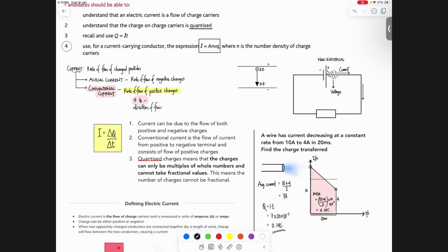So for example, a thermistor, you have heard of the thermistor, right? What does the thermistor do? As temperature increases, the thermistor's what decreases? Resistance, right? Now, V equals IR can't explain that, right? V equals IR doesn't explain properties. This one will explain that. This will explain why an LDR works. This will explain why a thermistor works. It'll explain why resistors increase their resistance when temperature increases, right? All of these are based on this last equation out there.